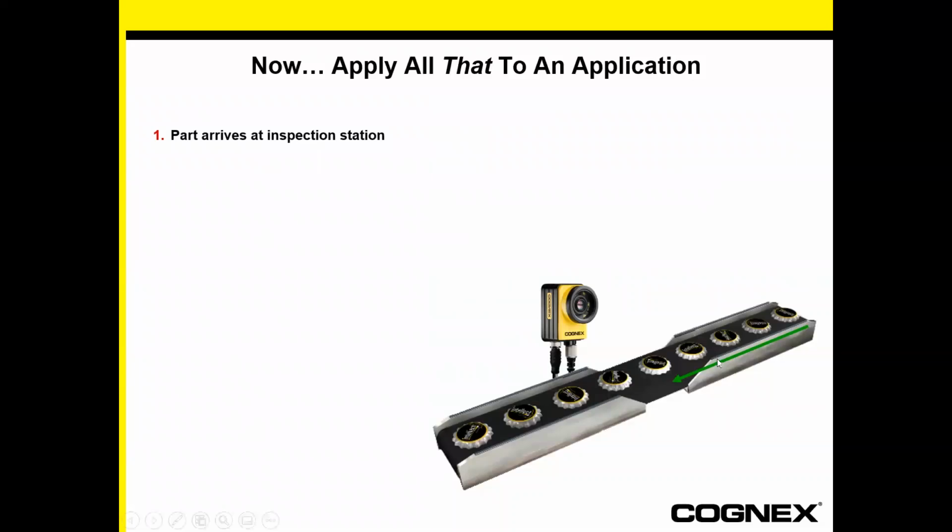So it could be a matter of changing the conveyor. So change the conveyor to blue. That way, it doesn't matter if it's white or black bottle tops, you've still got a contrast. Then the customer says, well, I do blue bottle tops. Okay, need to think outside the box. Maybe we backlight it. So have a PVC conveyor, put a backlight underneath the conveyor. That way you would end up with a silhouette. So the point I'm trying to highlight here is how you present the part can make or break applications, and you may need to change the environment to be able to inspect the product correctly.